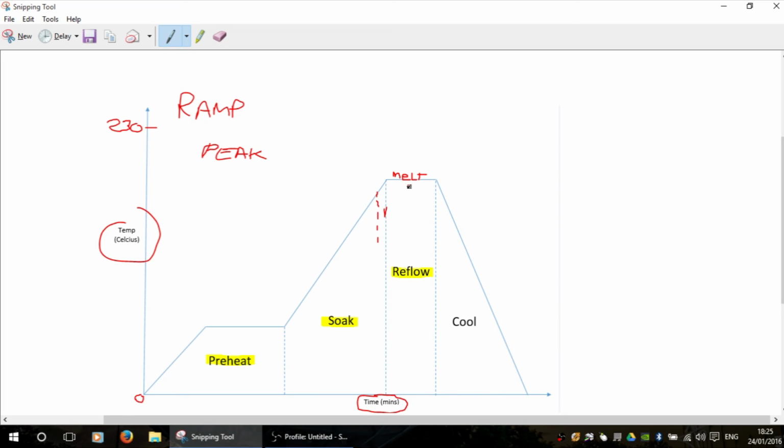And of course, before we lift it, what you need to do is give it something called the nudge test, which essentially is get the end of a tweezer blade or something of that nature and just give the BGA a really tiny tap on the bottom edge and on one of the side edges to make sure it moves freely in both directions, which tells you, of course, that the solder is melted and that you're safe to remove it without pulling pads or points on the board or on the BGA itself.